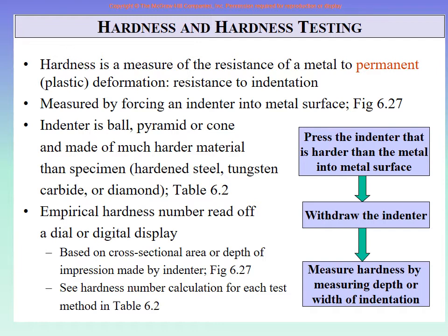If you have the correct answer, a very good answer would be resistance to permanent or plastic deformation. This is strength. Or in general, resistance to deformation. If a material has high yield strength, you will have to apply a lot of force before it can deform plastically.